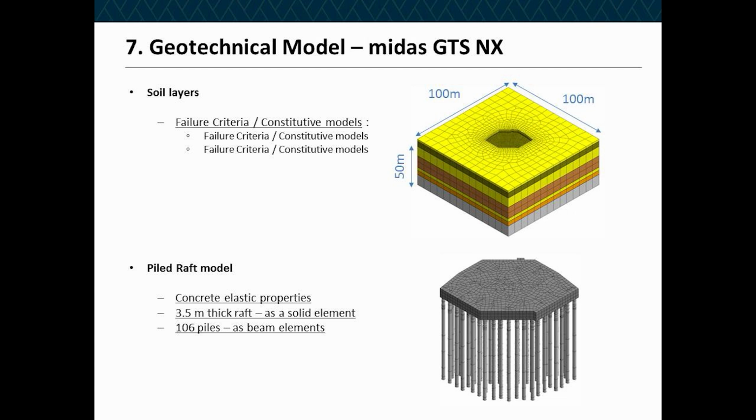This model is a more complex one with some properties that are not defined very easily. So based on other soil investigation campaigns that we have in the local area that also have laboratory testing, we have knowledge of the behavior of the clay from these deposits. Since there are some doubts about the behavior of clays, we decided to make 2 different models using 2 different approaches.